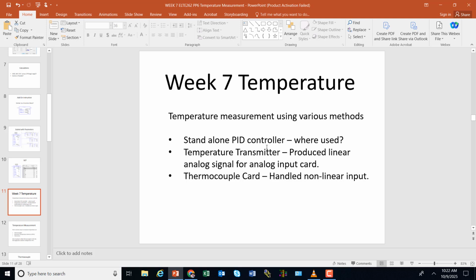The ones I got, they have a controller. They have a thermocouple you hook to them, and then when it reaches a set temperature, it turns on a solid state relay. So the whole thing, the relay, the heat sink, thermocouple controller, is like 20 bucks. All right. And so you're just gonna kind of mess with these. You can use these around your house if you have to control a little process.